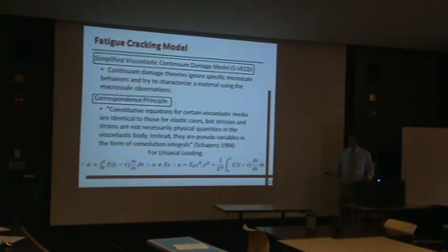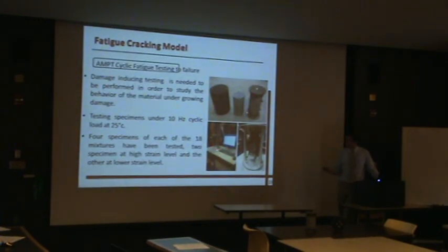And there is something else called the correspondence principle, which changes the viscoelastic problem to an elastic problem. I can apply Hooke's law, for example, by, instead of using the real stress or the real strain, I will use imaginary or pseudo strain. So by using the pseudo strain, I can apply elastic problem like Hooke's law and any other properties of elastic problem. This was developed by Schapery. This is the testing using the AMPT, and I will do it at 10 Hertz cyclic loading, 25 degrees C, until fracture of the